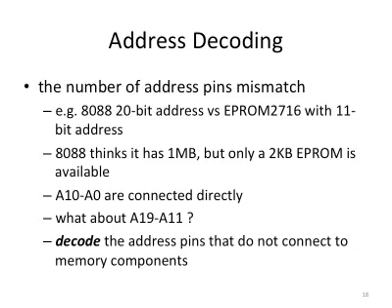We should decode the other address bits properly. Otherwise, you will supply your microprocessor with some invalid, garbage data, because you don't have something valid to put on the data bus for the processor to read.